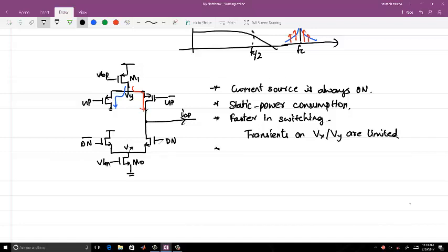The other thing which you can say in this case is that your up and down signals, right? These signals can be limited swing, that they do not need to be CMOS signals. Now, how do you generate it? That's a different case.